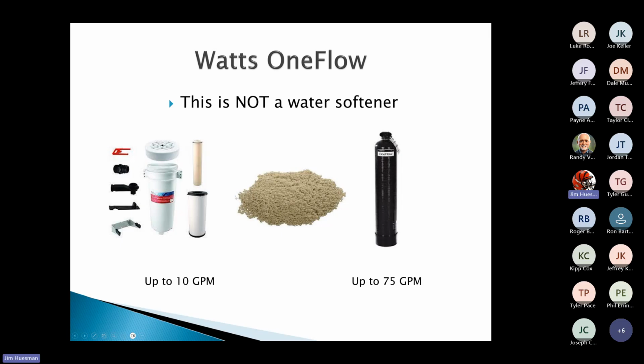One thing with this media, okay, this media is great, and it's good for up to 3 years. Now we talked about that little golf ball that's collecting the calcium and magnesium. But as it microscopically flakes away, obviously anything that's breaking down is going to get smaller. So what we'll tell you is if you're using a One Flow, either the Plus or just our One Flow tank, and again, it goes up to 75, we can get you 30s, 50s, whatever it is, that media needs to be replaced every 3 years. And the reason is at 3 years, that little piece of media in there has flaked away enough that we're saying, hey, it's not good.